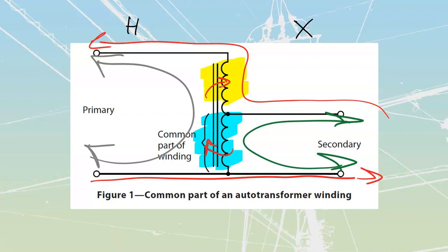So there are a lot of net benefits to them, but there are some disadvantages. The main disadvantage is going to be that low percent Z, that impedance. And because I've got a low percent Z, I'm going to get a large amount of fault current. You should remember how to calculate fault current from second year. Your fault current is going to be your secondary current, so I secondary, and you're going to divide that by your percent impedance. And if that percent impedance is small, the resulting number that comes out of here, your fault current, amps under fault, would therefore be quite large.